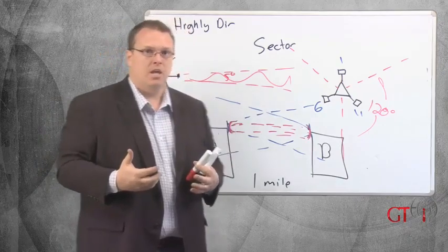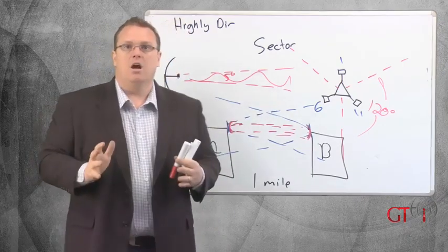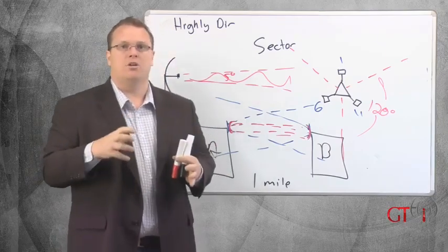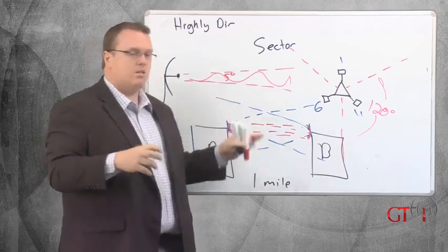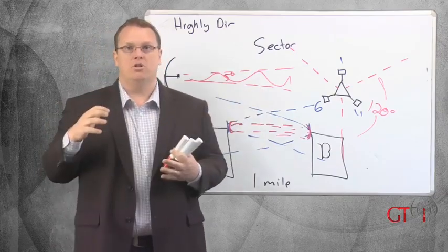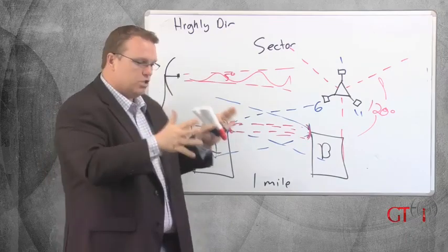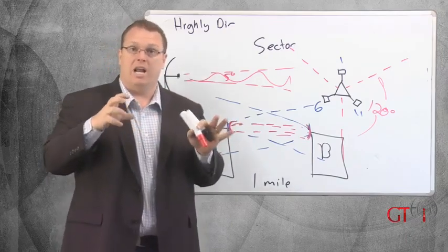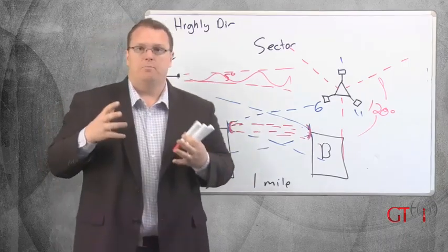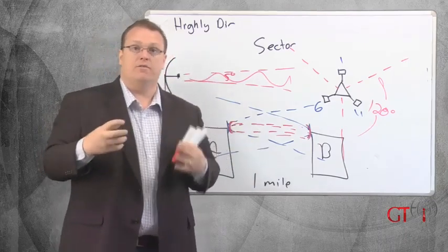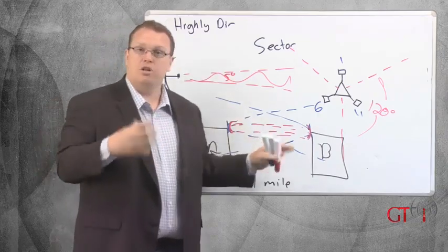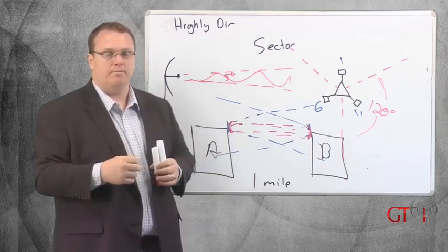So this was a long video. We talked about polarization, kind of an odd topic out there, but it's important to understand polarization when it comes to these antennas and antenna design. We talked about omni, goes everywhere, not as much gain. Semi-directional, covering just a portion of an area. A highly directional antenna like we've seen here. Patch antennas, panels, Yagis, just different types of antennas. Dish, grid, sectors, just different versions to achieve the same thing.